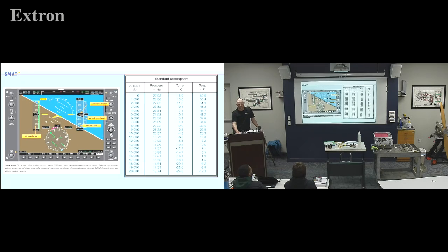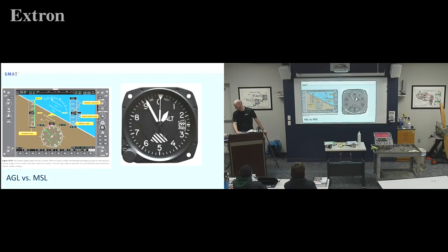You said it's a perfect day, you're referring to the temperature, right? It's not so much temperature as the pressure setting on the Kollsman window. So, we don't know, does it have a temperature? Yeah, bottom right. Bottom left, maybe? Oh, 7 Celsius. It's a little colder than the perfect day, because 15 minus 4 would be 11 degrees Celsius if it was an absolutely perfect day, but we're getting off into the weeds.